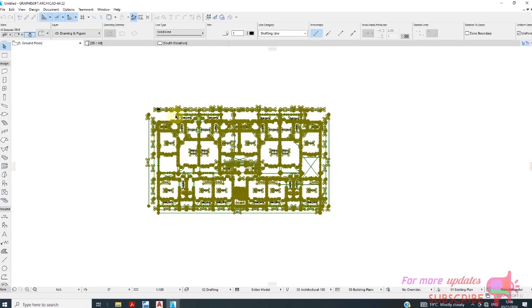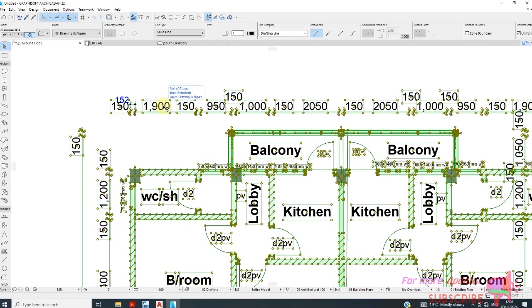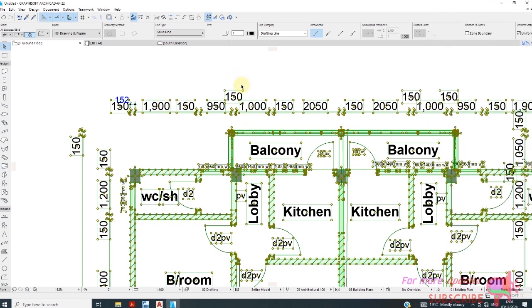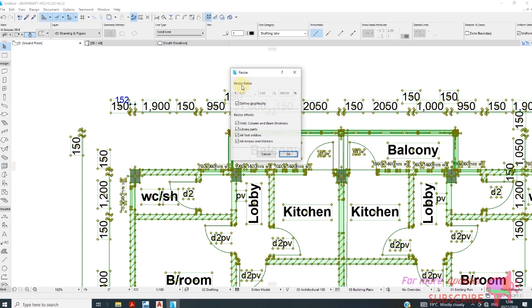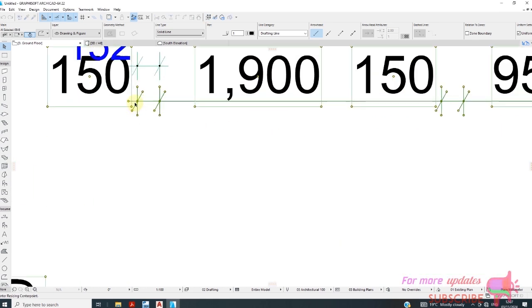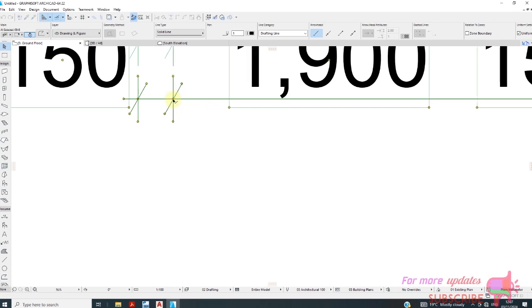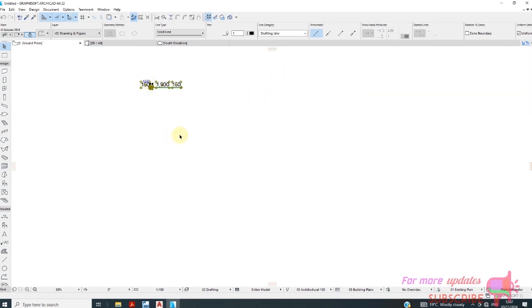Select everything. Okay, that is Window plus K, Control K. That is Control K to resize, and then OK. I want to resize using that point and that point. Holding Shift, D should be 150. Enter. Now the drawing is to scale.